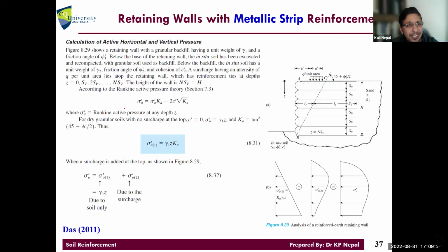Again, there are a lot of theories involved. You need to understand this. Look here. This is the bottom of the foundation, and this is the failure line. Before the failure line, we call it LR, the length required before the failure line. We can easily calculate it from the proportion. Then we call the equivalent length after the failure line LE. So when I add LR plus LE, it becomes the total length of reinforcement.